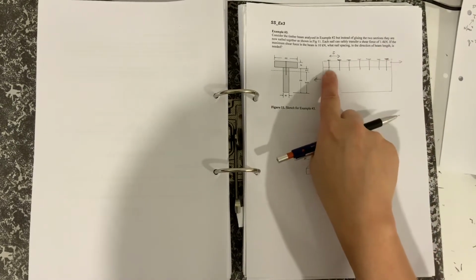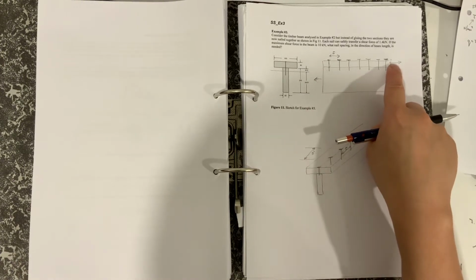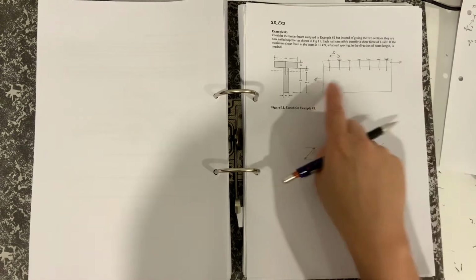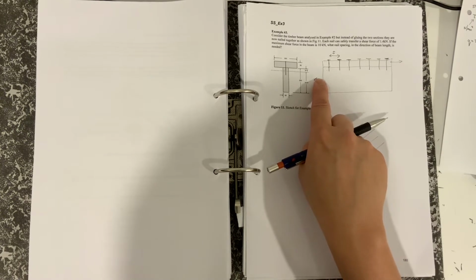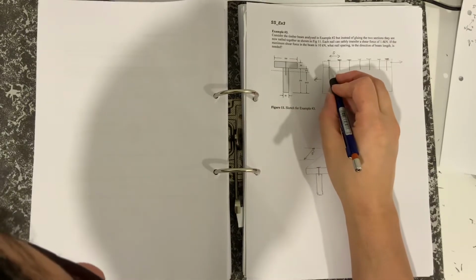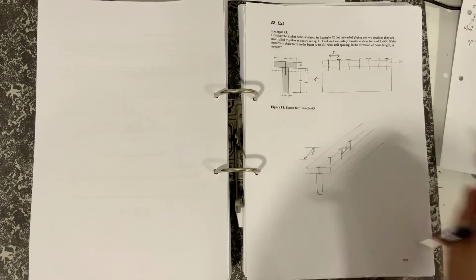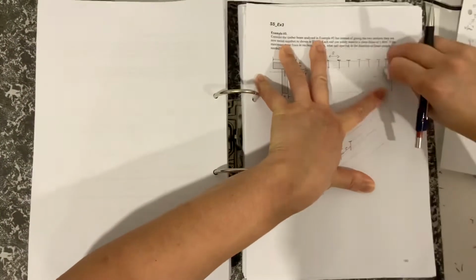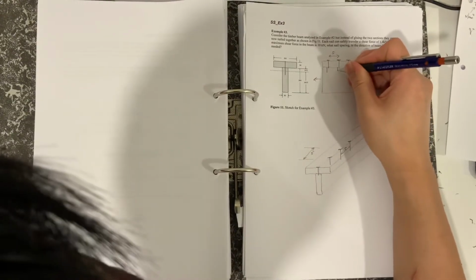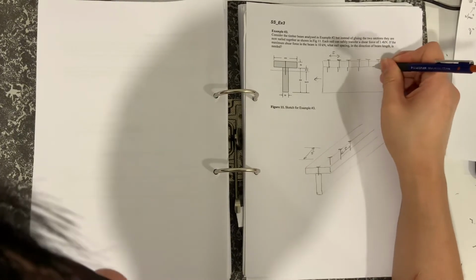And then if you did an experiment and you pulled these two apart, so that one is in shear in that direction, and this one here is in the opposite direction, you could say that after you've pulled it over, each nail breaks, or each nail is sheared along that shear plane.